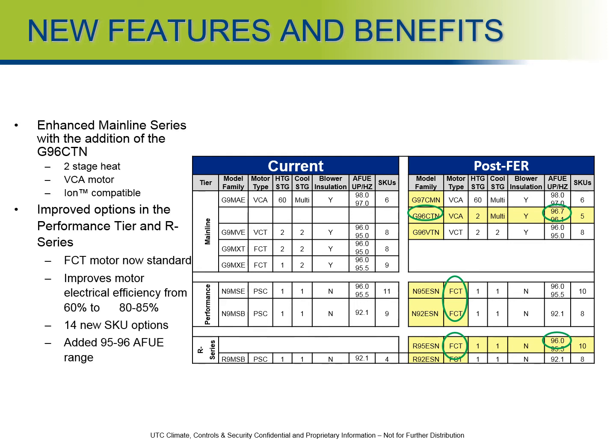So in cases where you have a slightly restricted air filter or a slightly restricted evaporator coil, your variable constant torque motor is not going to overcome that added resistance.